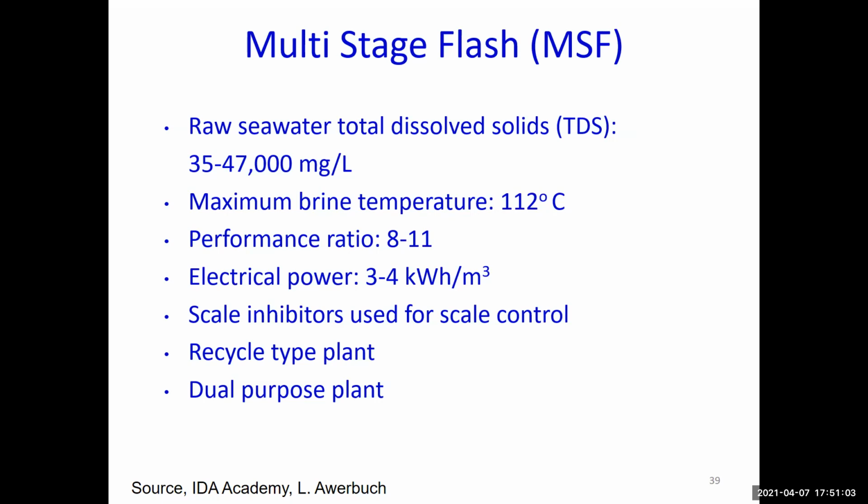I have to tell you that the MED unit is just needing something close to 4 kilowatt hour per cubic meter to operate with all pumps and heating requirements. So the MSF basically is more demanding in terms of power, but it is the most reliable and the most experienced kind of desalination technology.